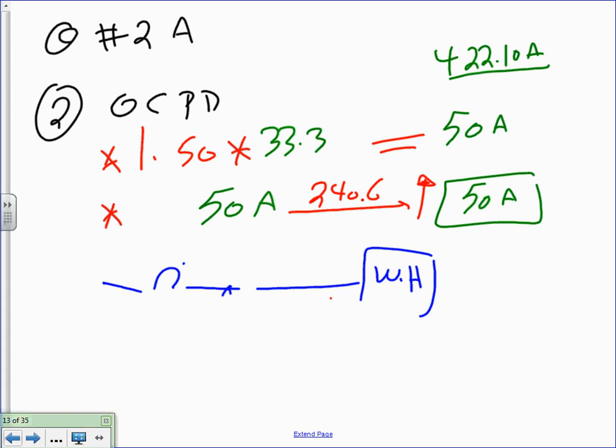All right, so we're done. Here's where we do the check. Remember how we do the check, guys? Any question about the 1.5 to 422.10(A)? 430.52 to get the size for that. The 1.5, it's coming from 422.10(A), I believe. No, where you're looking for the standard size of the OCPD, 240.6, 50 amps.